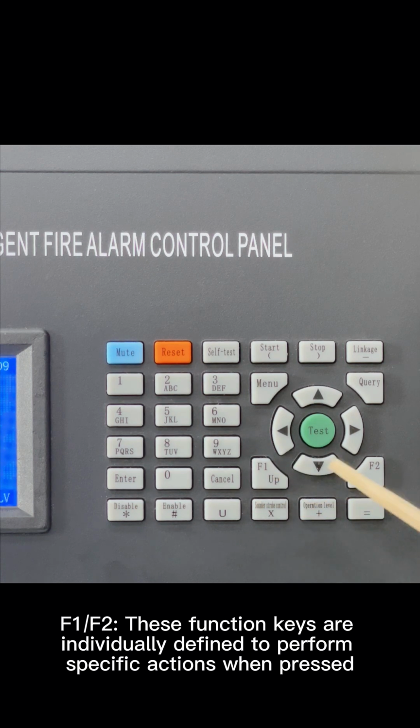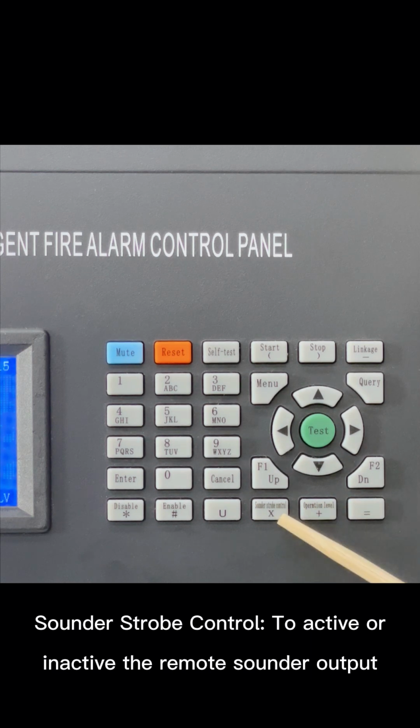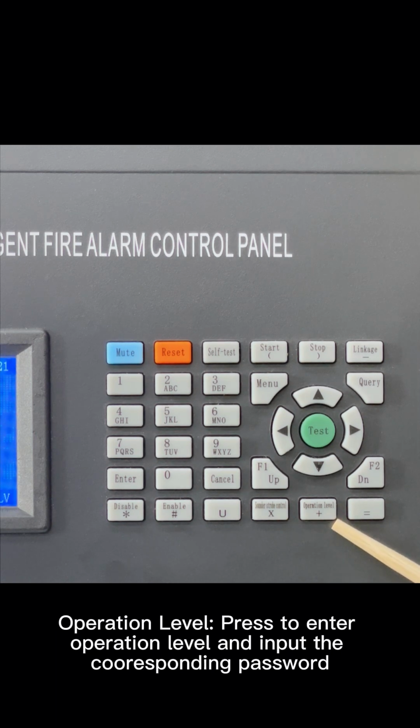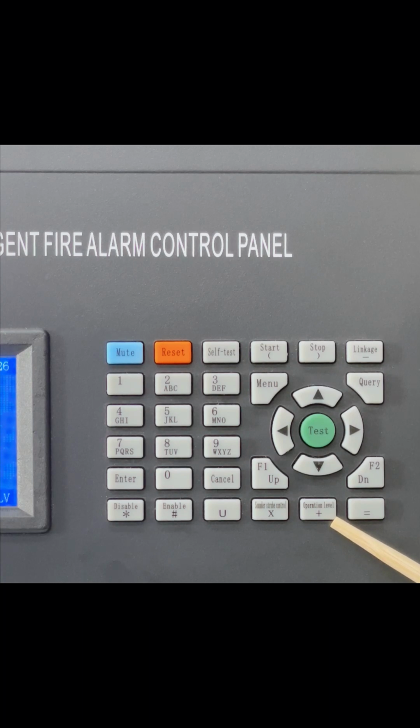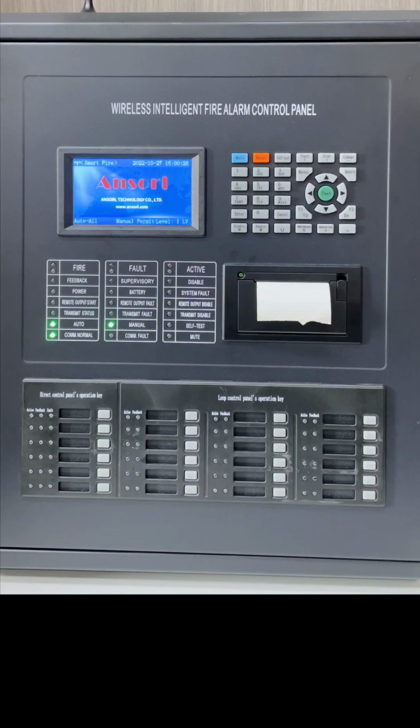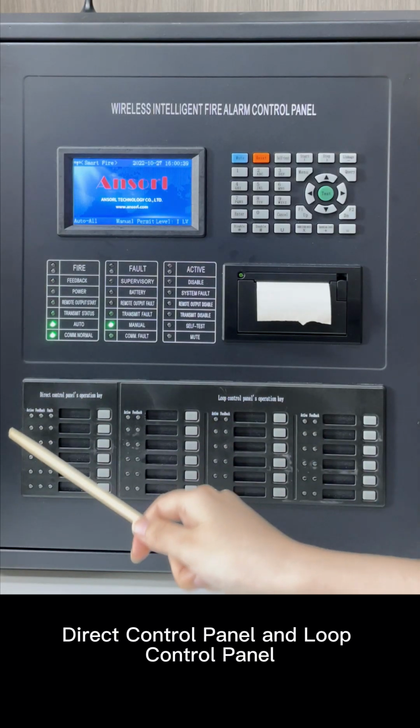F1/F2, these function keys are individually defined to perform specific actions when pressed. Sounder strobe control, to activate or deactivate the remote sounder output. Operation level, press to enter operation level and input the corresponding password. Equals, to input the equals sign, or to switch input method. Direct control panel and loop control panel.